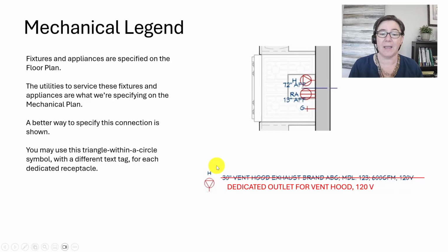While I'm here and looking at this text tag, I'd like to remind you to use a minimum of 1/8 inch high text. Sometimes these little tags can get really small. Make sure they're big enough to read.